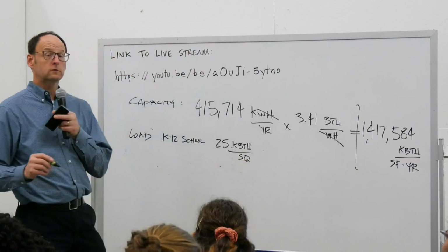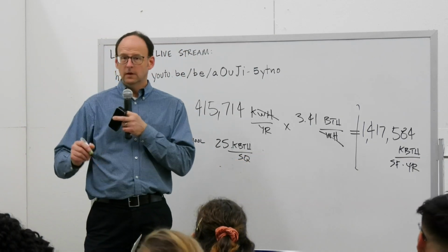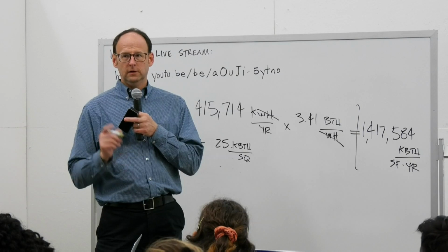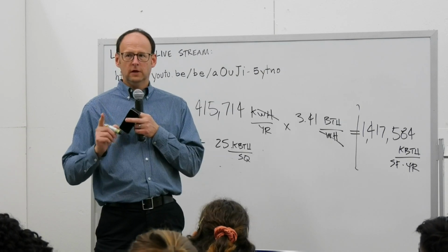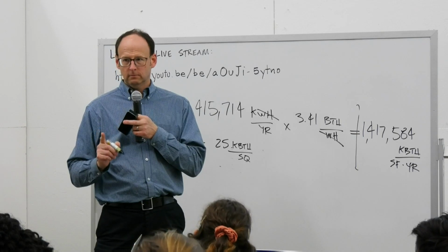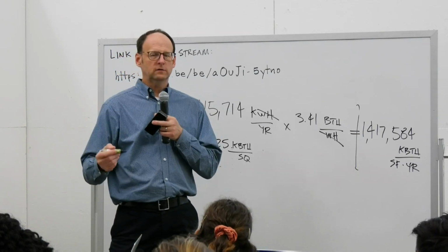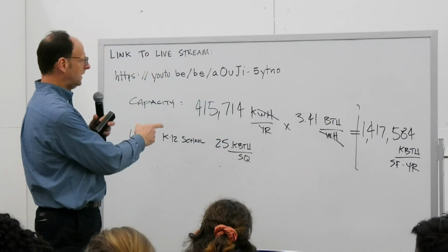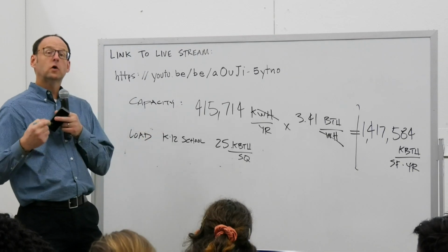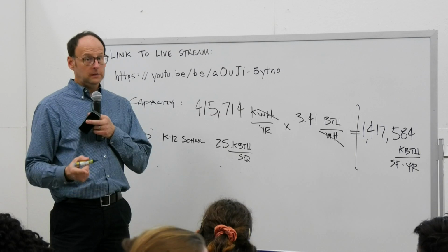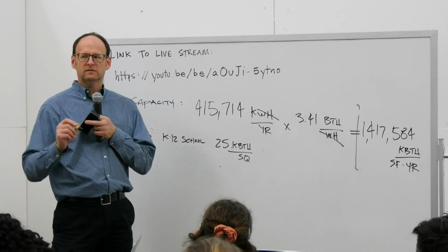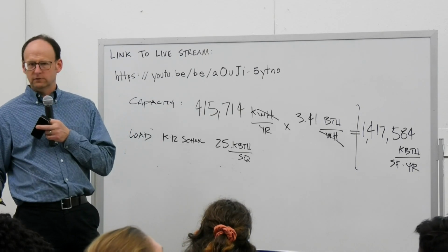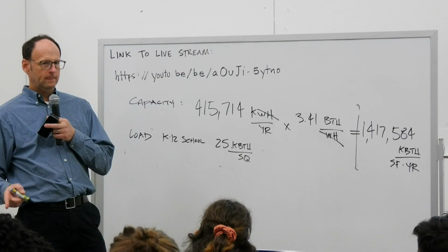It was actually a great question for your students, Michael, because we talked about this. How did we incorporate energy efficiency into what Bill did earlier in his presentation? He did something to establish a certain energy intensity. Do you remember? Michael's asking the question, have we incorporated energy efficiency? So let me turn that question back to all of you. Did Bill, when he established that 25 kBTUs per square foot, establish some target efficiency? He did. He said we're going to take CBEX and we're going to take 70% of it. So we're 70% of a CBEX typical building. That's where the energy efficiency got incorporated. Do you remember that? All right.